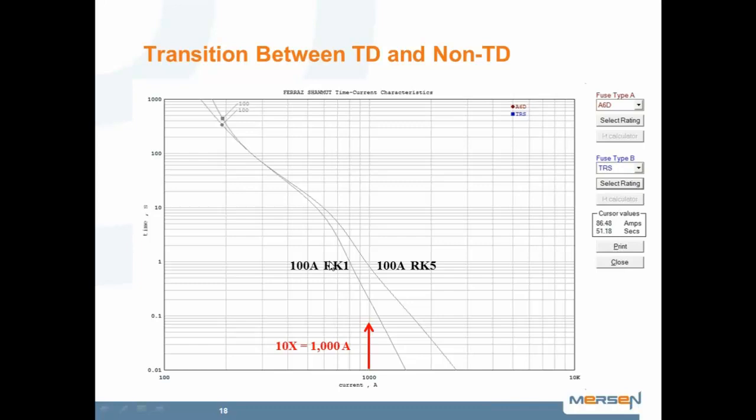And if you think of a typical application, if you have a fuse that's not more than 80% of the continuous rating of the circuit, or if you are using it for motors, use sizes approximately 175% of the motor full load current, and the motor full load current is related to the inrush current of maybe 7 times.